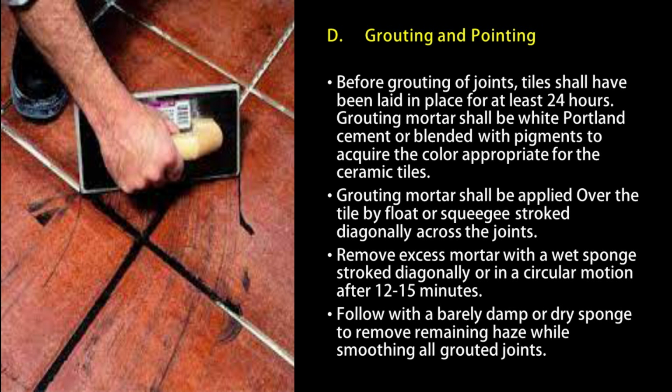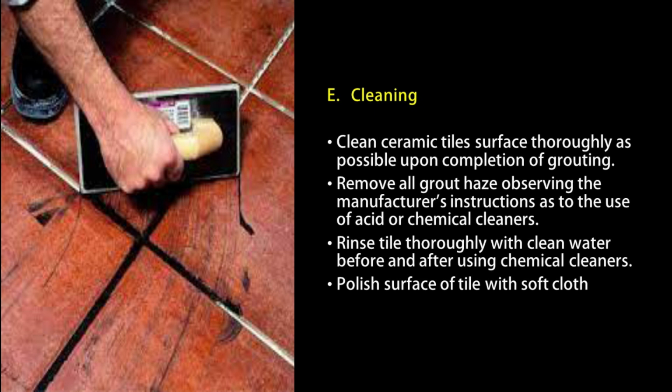Remove excess mortar with a sponge, stroking diagonally or in a circular motion, after 12 to 15 minutes. Follow with a barely damp or dry sponge to remove remaining haze while smoothing all grouted joints.